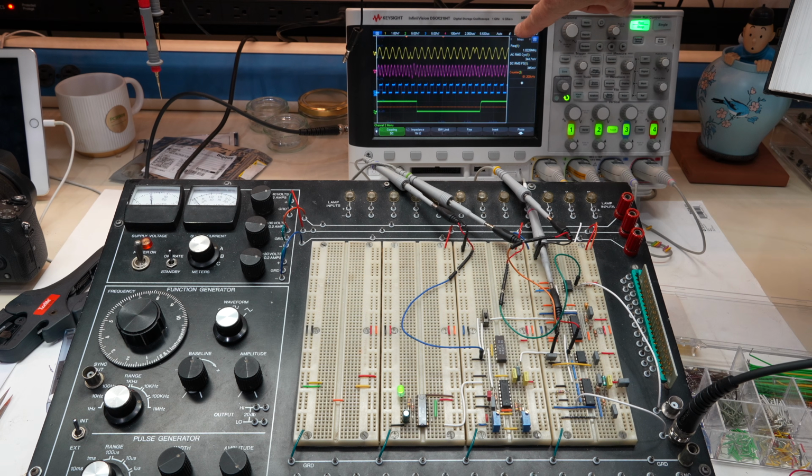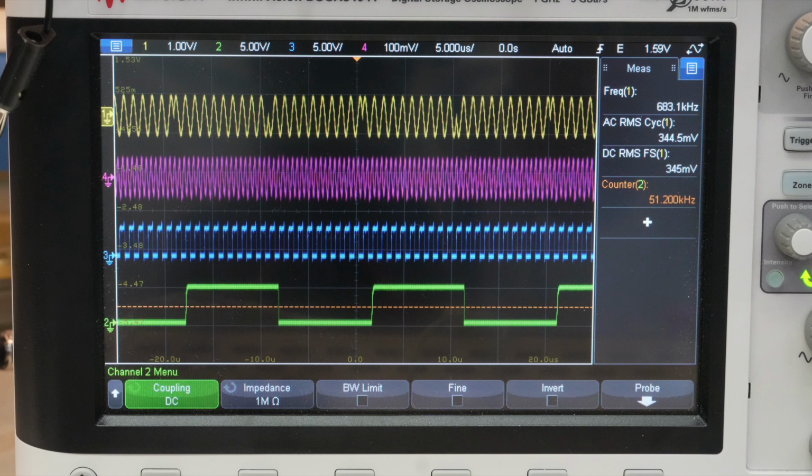But I arrive at this pleasant result where you have the BPSK signal coming in. Here you have the double signal. Here you have the PLL divided by 2. You multiply this by that and put it through a comparator and you get your bit back. Awesome. And voila, it looks almost like in the theoretical presentation, all analog, no computer or DSP involved.